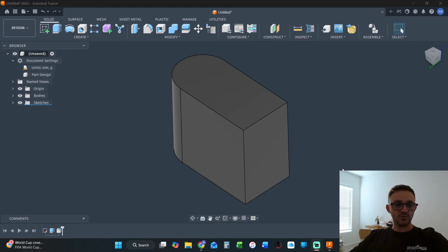So, extremely useful. And the one that I could think of that I use the most often is going to be for something like mating a helicoil or a spring. So think of just a piece of wire that's wound in a helix, essentially, anything like that. There's no conical or cylindrical face to constrain the center of that part to the hole or the shaft or whatever it is it's going to be mating to in an assembly.